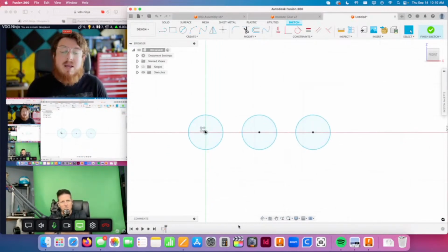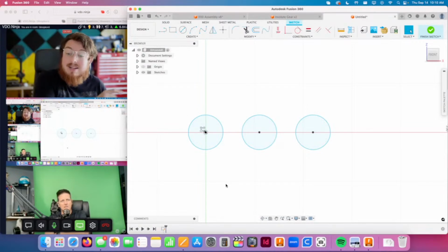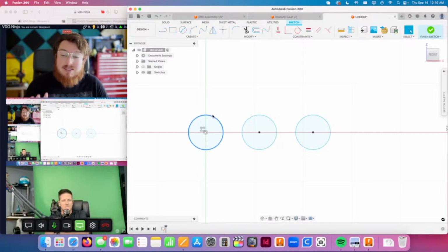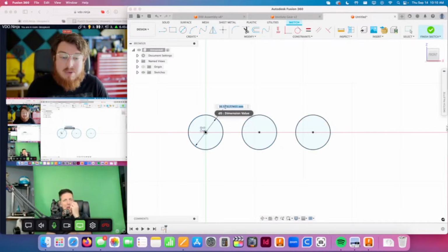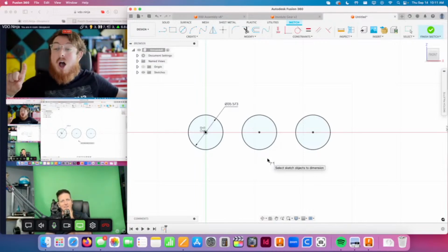So that's because the timeline is basically built up of features. If I want to make a cube with a hole and rounded corners, then you started off with a sketch of a square. You then extruded it to a cube, then you added features to it, and then drilled the hole through. So all those are individual features. Whatever you do inside the sketch is only represented by this one sketch feature. Because then someone may go, we should add a rectangular pattern in here, and then someone goes, well, then I want to add the dimension in the timeline as well. And then it builds very quickly. Then you go, oh gosh, if I just want to make a semi-complicated sketch, my timeline is now unearthly long.